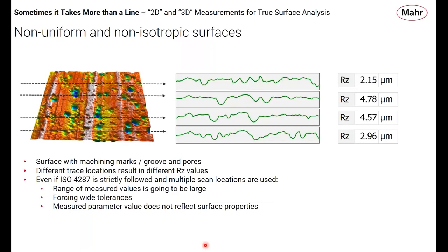You may say, looking at those green profiles on the right, oh, well, Chris, actually, it's obvious where the pores are and where the grind marks are looking at that. Well, I'd counter by saying it's obvious where the pores are versus the grind marks, because you can see where they are on the image on the left, and you associate that when you look at the image on the right. If you just had one of those profiles and nothing else, you would have no idea what's a pore and what's a valley, really. Or you might be able to make some educated guesses, but you wouldn't have much to stand on.